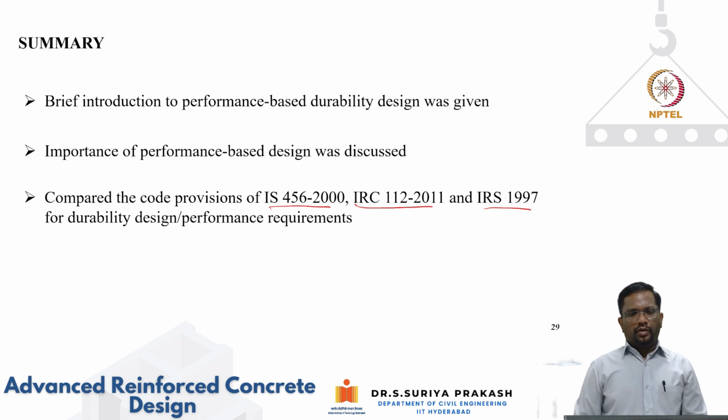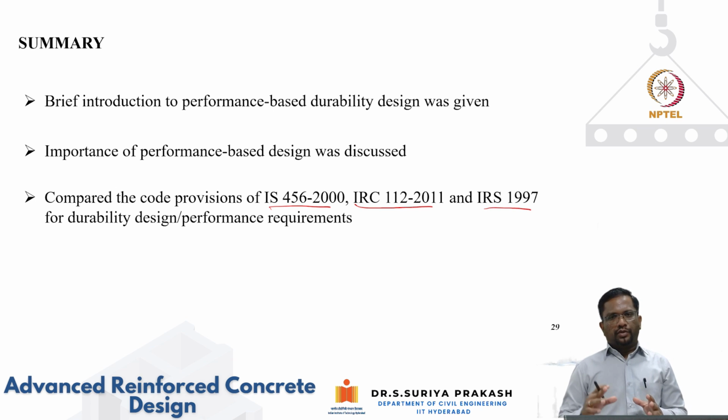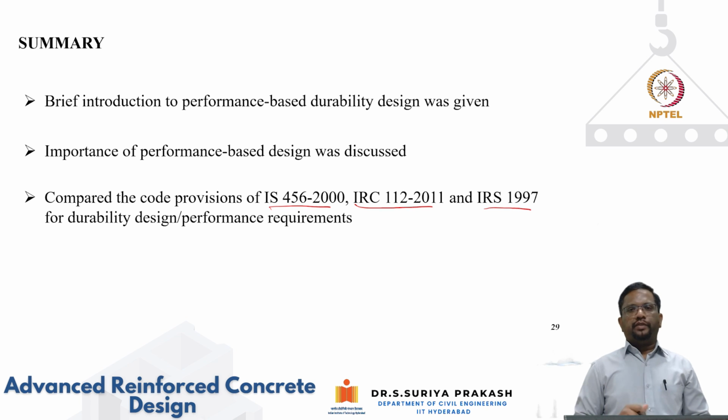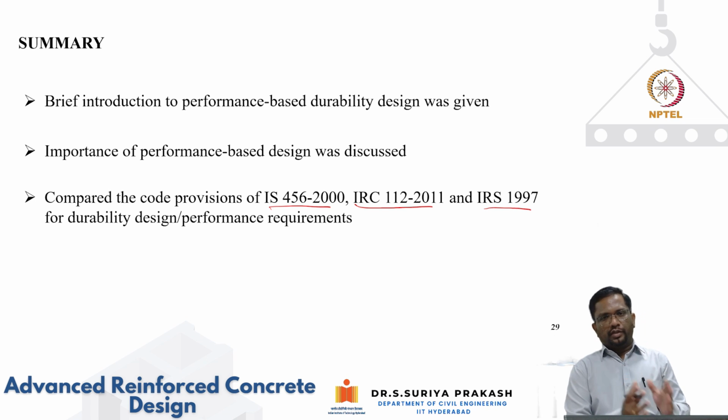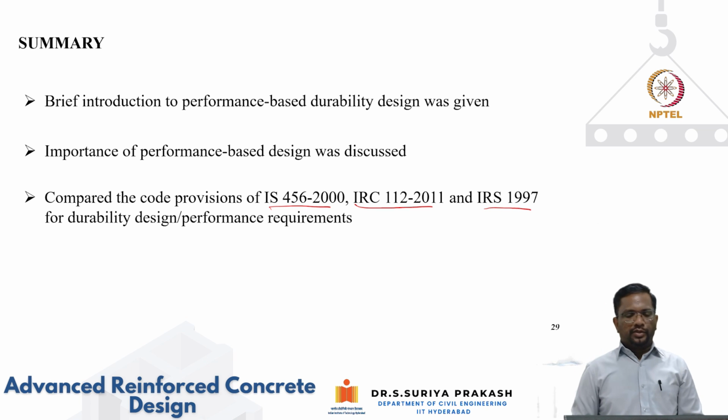Right. So again, though this course is on advanced reinforced concrete design, where we're going to talk about design of elements for various actions, durability is a very, very significant aspect. And even in IS 456, as I've told you, it is undergoing a major revision where durability is going to be given major impetus, and you have to not only design for strength and serviceability and other limit states, durability also you need to explicitly design so that the structures are going to be performing without much durability issues, and are not requiring more amount of repair. So that is a thing.